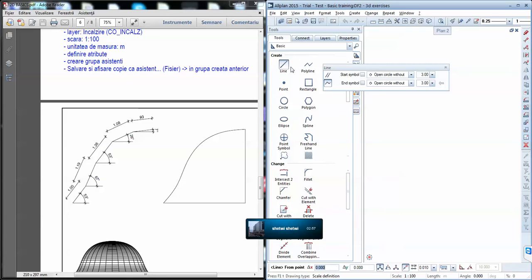We'll draw a simple line, or we can use a polyline, it doesn't matter. However, what is important is the way we'll enter the coordinates. Yesterday we used global point, then delta point, where the global point was in an absolute geographic coordinate system, while delta point was referring to a previously inserted point. And now we'll use polar coordinates. Polar uses a coordinate system which needs an angle and a radius in order to draw a shape.